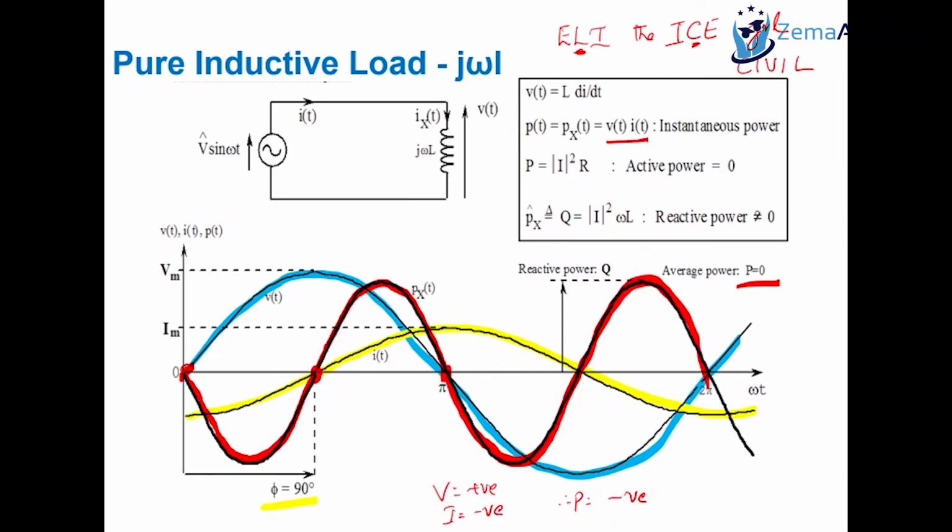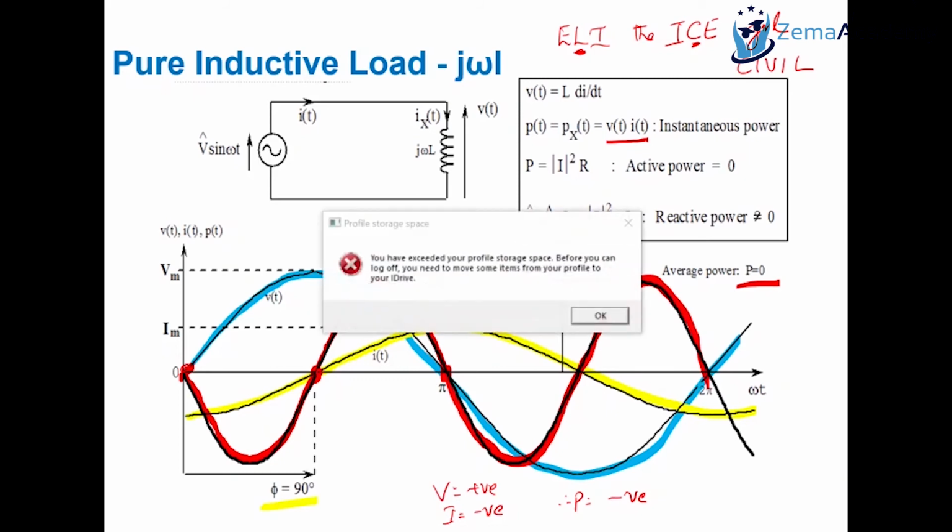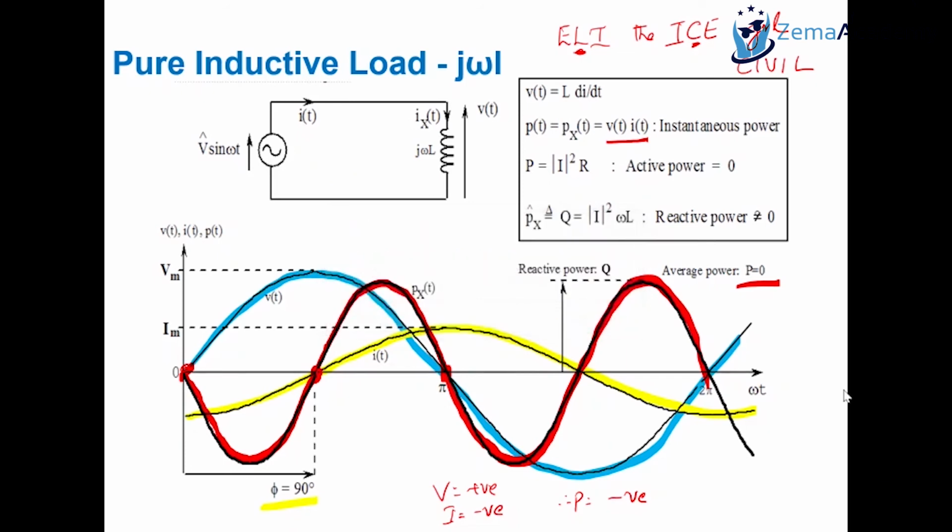Just by itself, it doesn't do much useful work. Now, within a transformer is again an inductance. Although we always say that the reactive power, which is what we're seeing now, doesn't do any useful work, bear in mind, in a transformer, the reactive power is what magnetizes the core. And the core magnetization is the key essential for the transformer to work.